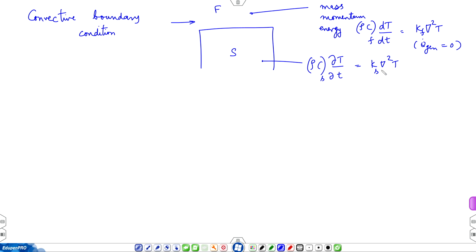Now, this is very much like the two fluid problem we had studied, and then there was an interface. We had the momentum equation in one fluid, momentum equation again in the second fluid. Here we have applied the energy equation in one medium, energy equation again in the other medium. You can have solid and solid, solid and fluid and fluid, all possibilities are there. And then you have a demarcating interface. So, you solve these equations individually and then you have to blend them at the interface. So, there are interface conditions. What are the interface conditions?